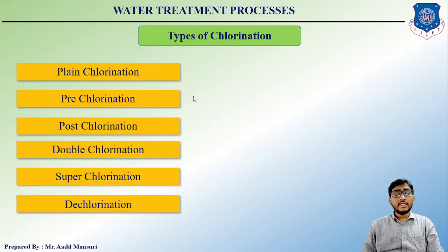Okay. Next is post-chlorination. So post-chlorination, sometimes known as just chlorination, is the normal standard process of applying chlorine in the end, when all other treatments have been completed. While treating normal public supplies, post-chlorination is adopted after filtration and before the water enters the distribution system.